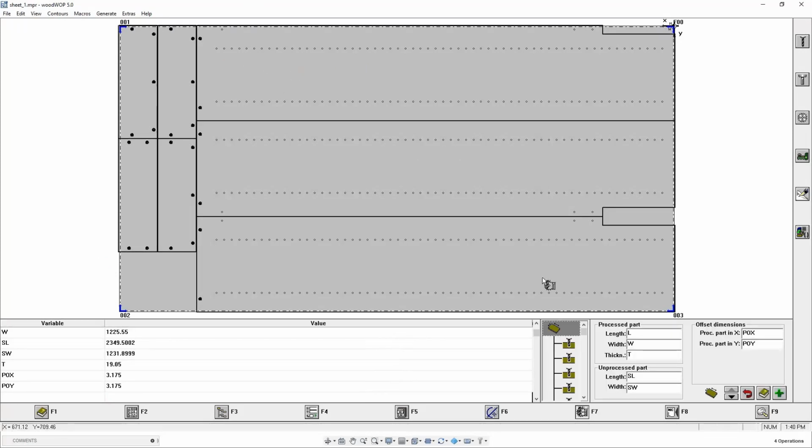Okay, so it's taking some time to load. That's fine. I can make the file size smaller if you want. All right. I can use a half-inch compression bit for the 2D pockets and not use a step down. Just plunge into the hole and route it out. Okay, I can do that. What else, guys? So I have all the drilling macros. I have the routing macros. Okay. So that's the program one, sheet one.